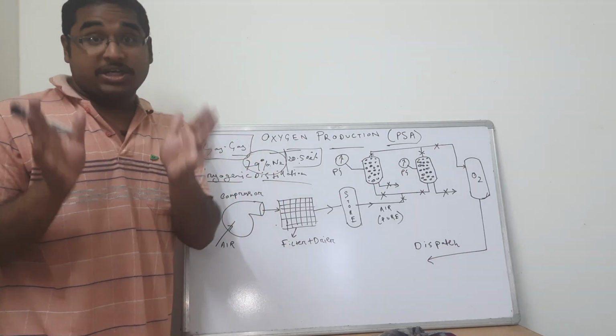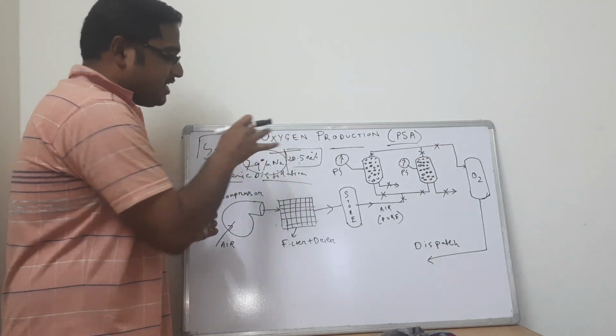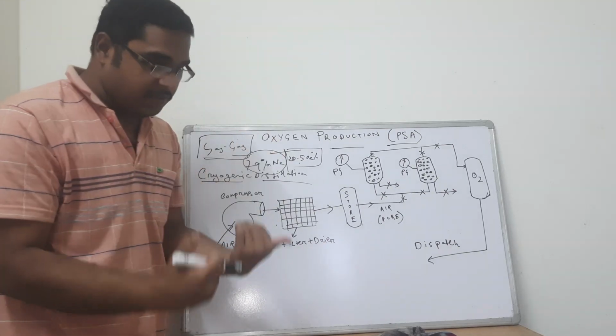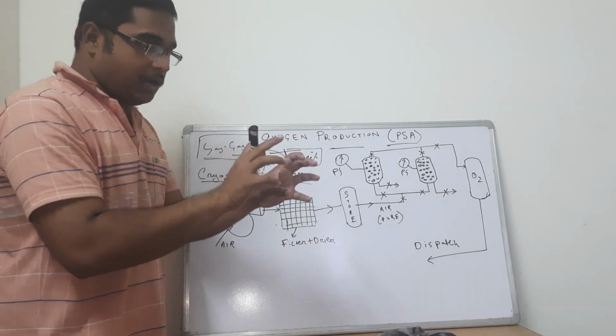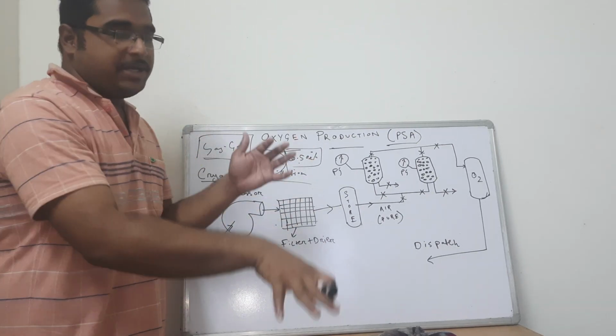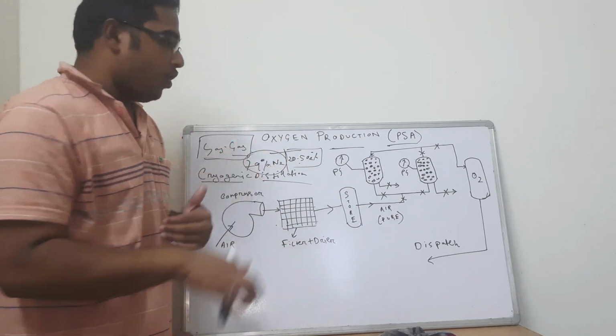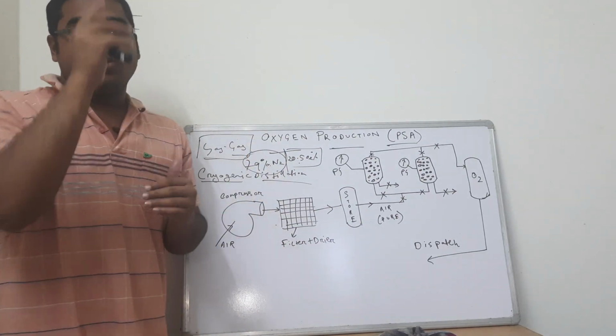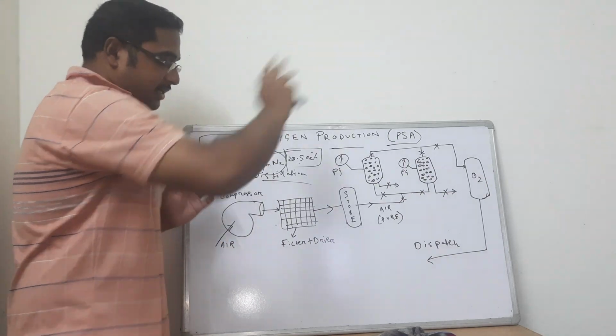And the other one is cryogenic distillation, which we are not going to discuss, but just giving an overview of how it is done. It is first converted into liquid, both nitrogen and oxygen, and nitrogen prevalently remains as liquid in the bottoms of the distillation column, and under those conditions oxygen tends to form vapor and get separated from nitrogen and is collected at the top.